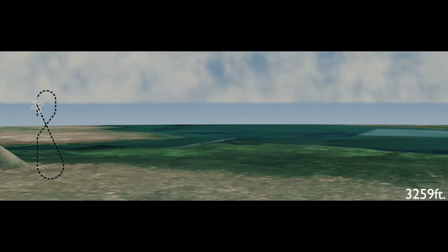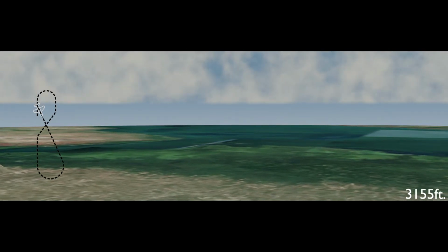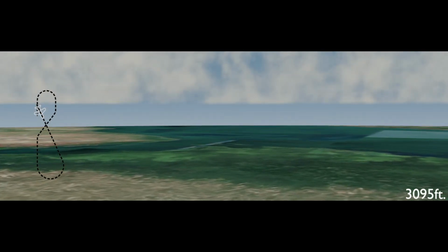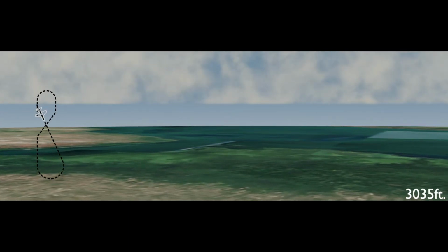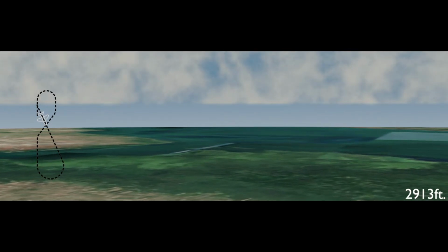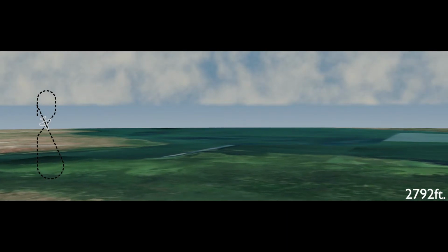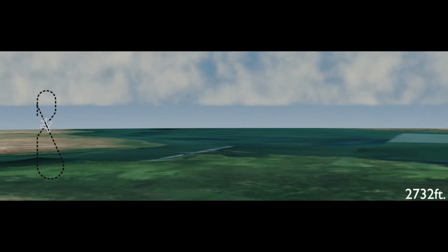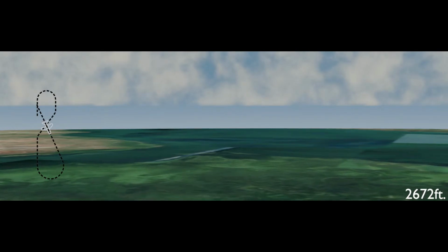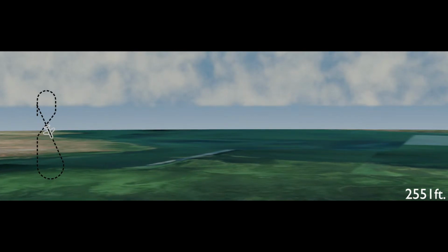The video starts overhead Podgorica VOR, Papa Oscar Delta, with the runway in sight at the bottom right of our view. The aircraft's descending from 3,500 feet on a track of 159 magnetic with an airspeed of 180 knots. Here in Podgorica there's high ground around the airport with an MSA of 9,900 feet to the east and 8,500 feet to the north. Following the prescribed tracks will keep us clear of the high ground, even at night when we wouldn't be able to see it.